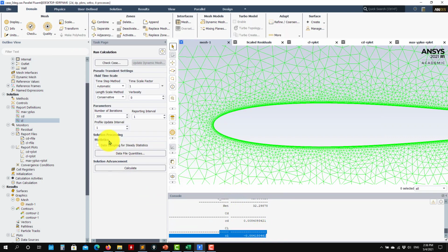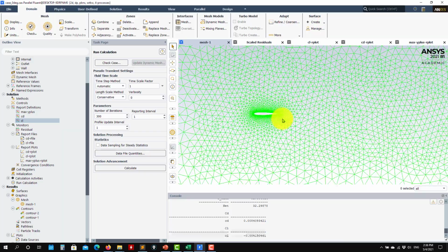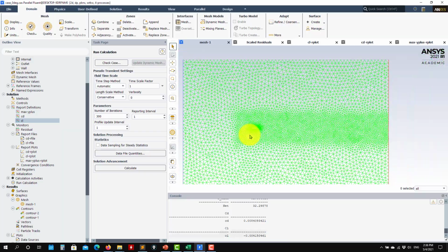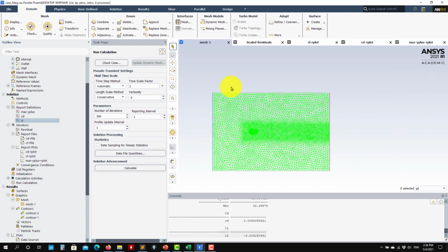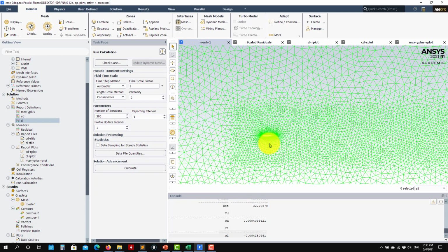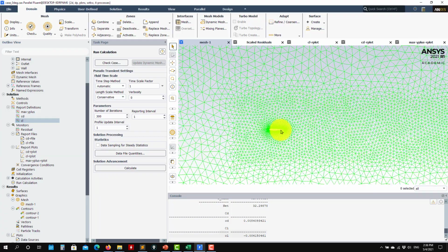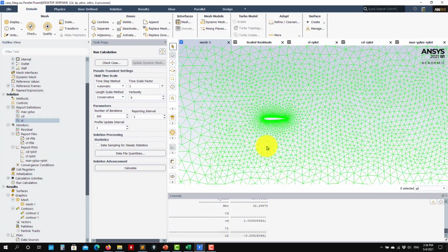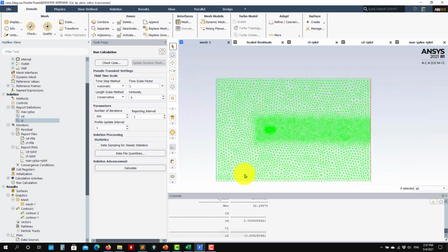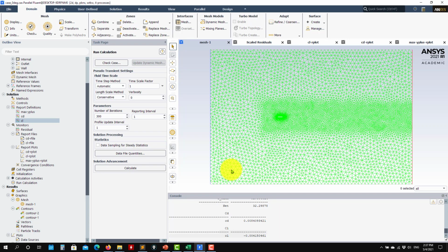So we have a good validation for 0 and 4, but what I want to change now is this angle. The advantage of having this mesh, you put it at 0 degrees and then you rotate this angle, is that you can sweep all angles of attack, okay, without modifying the mesh. Instead, if you want to modify the geometry, you will need to do the mesh for each angle, okay? I prefer to do it like that, but it's up to you. We're going to see that there must be the same or similar results, okay?